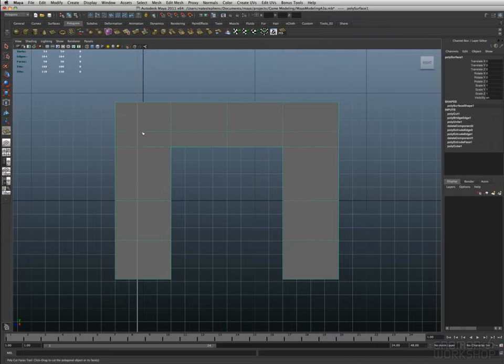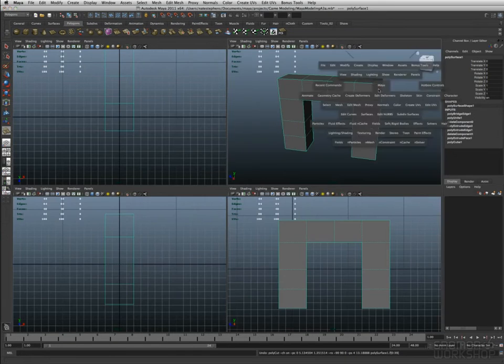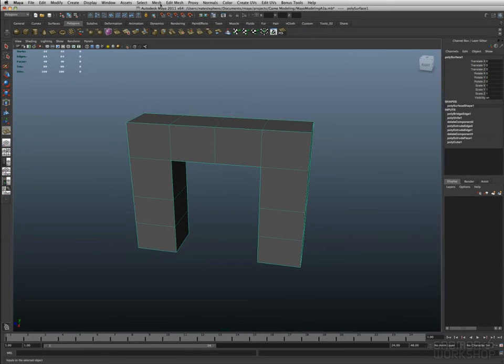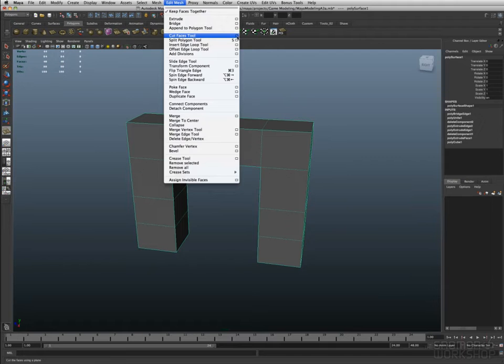And in this interactive mode, if I hold down Shift, I can now constrain the cut to 45-degree angles, which is really useful for just kind of adding more subdivisions to your geometry or doing kind of more complicated, precise cuts. And now I'm going to show you some of the other ways to use the Cut Faces tool.